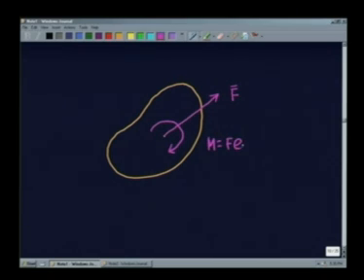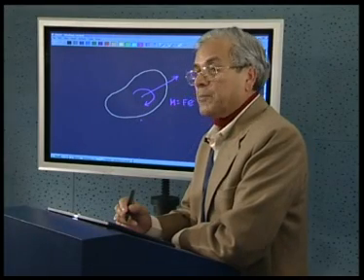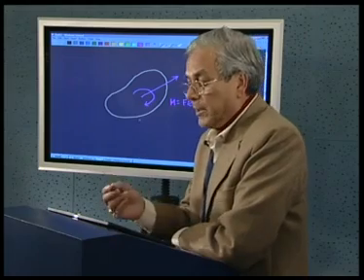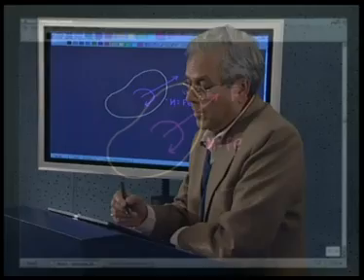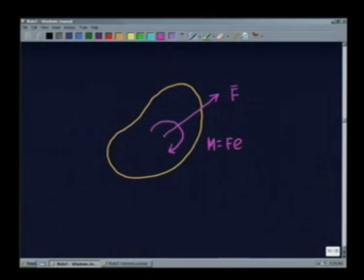Now, you will notice that I have not put a moment vector here, because in plane motion all angular quantities, like angular velocity, angular displacement, moment, can be represented by algebraic quantities. Say we may consider that if it is in the clockwise direction they are positive, if anti-clockwise they are negative. So, their summing up or subtraction is just like an algebraic quantity, whereas forces have different directions, and so they need to be represented by vectors.